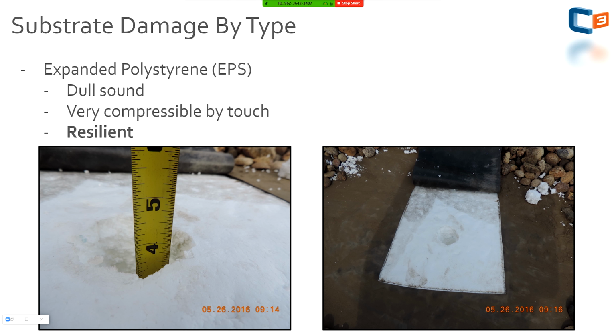This is a good example of a ballasted EPDM roof, and again, why these are very difficult to get bought. Oftentimes they're over steel decks. They're usually commercial applications or concrete decks. They have closed cell, very resilient insulation types. EPDM is very resilient. It's very resistant to impacts. And then you have stone sitting on the roof. So you can imagine all of its components are very difficult to damage.